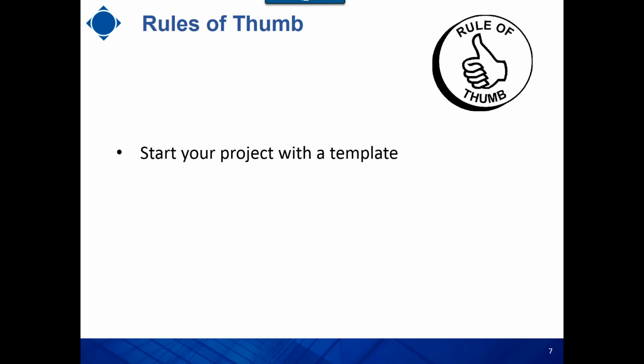Like back then when CAD World started implementing templates to standardize CAD production deliverables, the same concept exists in Survey World. When we start our TBC project or any survey project with a template, we make sure we have the standards in place before importing any data into our projects. Always, it's a good idea to check against existing control. If you have used some control points to georeference your point cloud, definitely make sure you check your point cloud after importing against those control points.